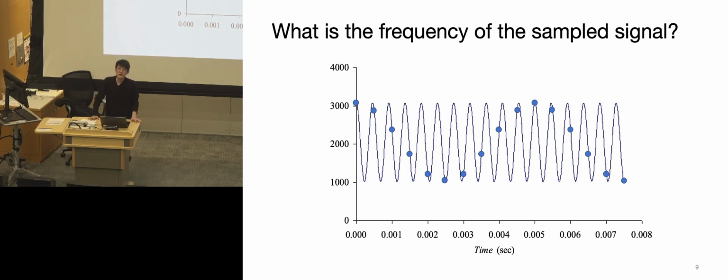In practice, most of the devices you interact with, unless they're super bare, all have some form of what they call anti-aliasing circuits. It's essentially an RC circuit, a low pass filter, and they will give you a number in the data sheet of what frequency range it senses.